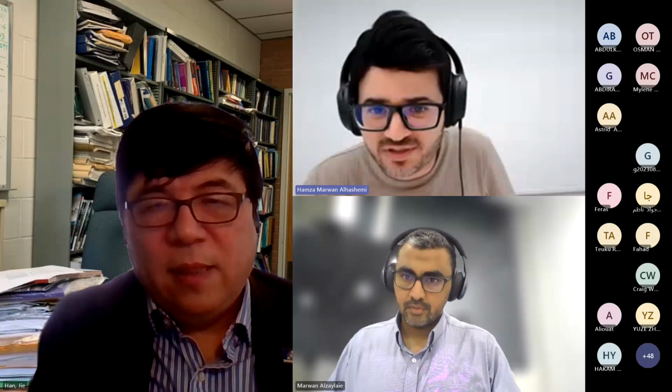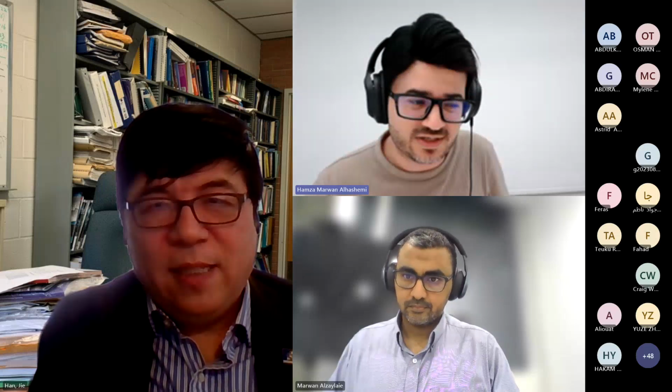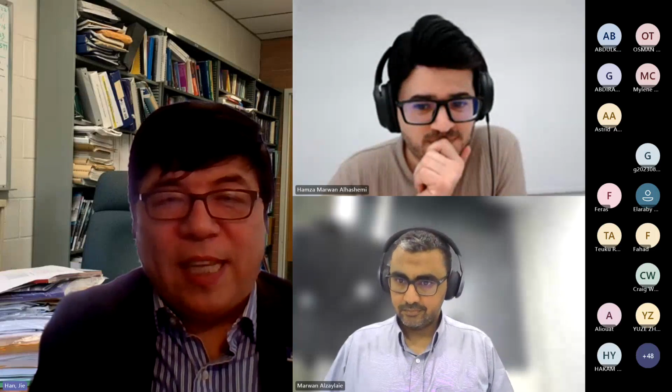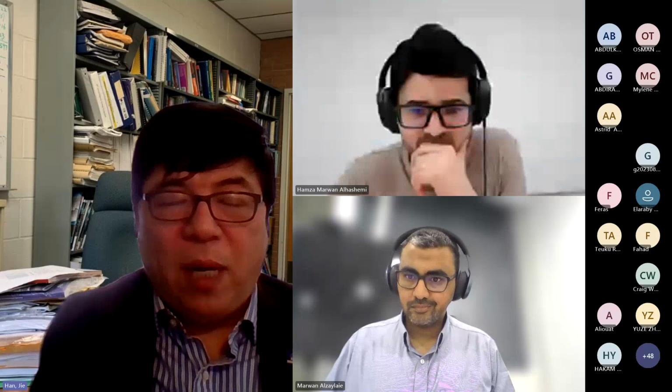Another last question, I believe, from Ahmed Awad. How about the durability of rigid inclusions without reinforcement? Are they considered durable? Durability would be the same as concrete, and how durable concrete is in the ground would be the same as this one. But I don't think it has anything to do with the steel reinforcement. Steel reinforcement basically relates to whether there's a tensile force, whether there's bending or not, right? In terms of material durability, I don't see any problem for concrete in the ground.